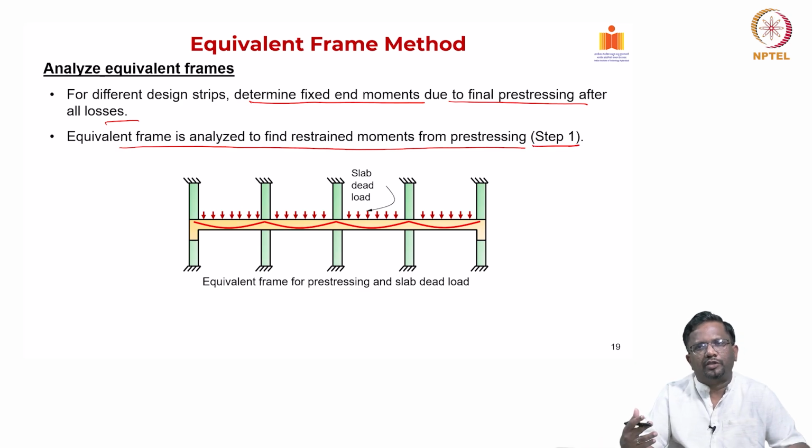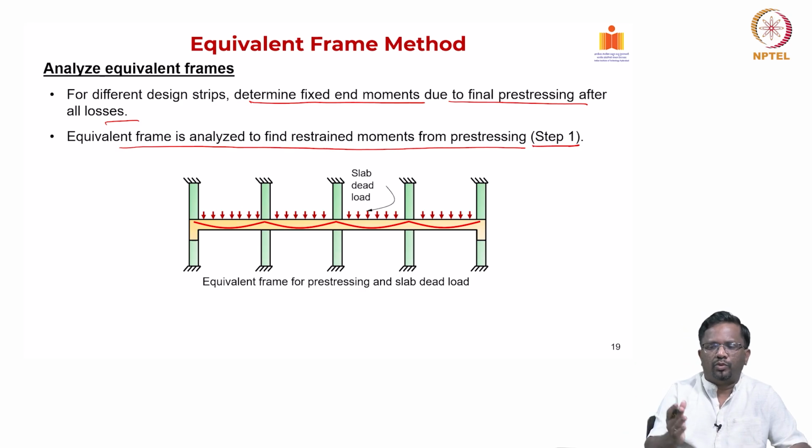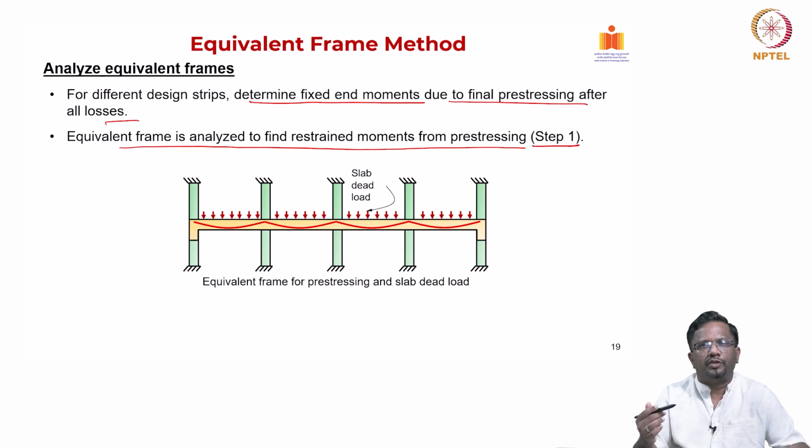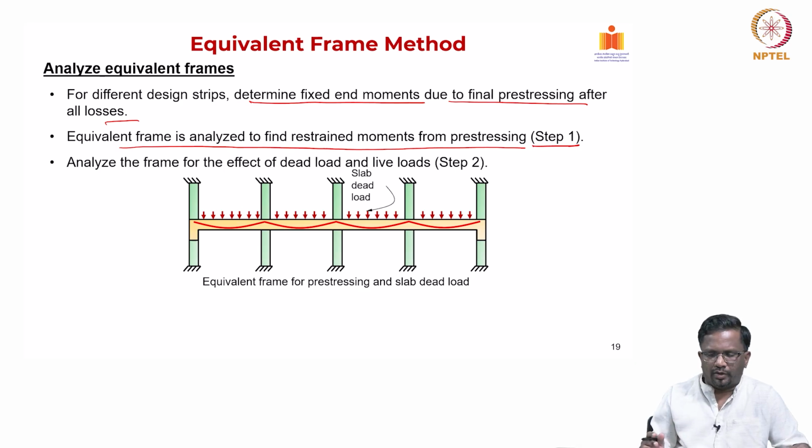Of course, in the next week's module, we are going to go through one detailed example of how to do a post tension flat plate. Then you will know how to calculate these moments, and, as I told you, we are also going to compare these results with what a commercial software package produces. That we will discuss in the next module. The first step is anyway to include the effect of pre-stressing and then find what kind of restraint moments are produced. So that has to be taken into account, right.